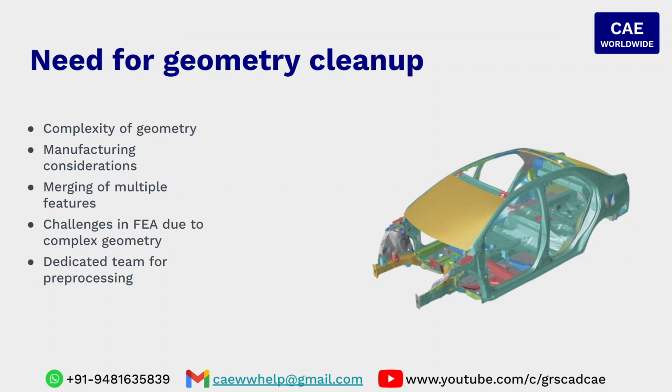The complexity of the geometry generally comes especially in the automotive or aerospace domain, where the shapes of the geometries play a very critical role. When the geometry comes from the design department to the simulation department, geometry complexities, imperfections, and missing geometries can be expected. That can be because of inadequate experience of the engineers, or geometry missing at data transfer or data conversion, or changing the format of the file from the native software to a neutral format.